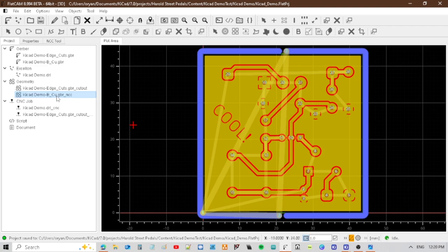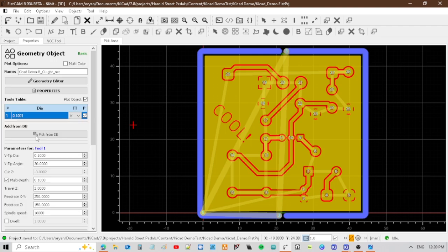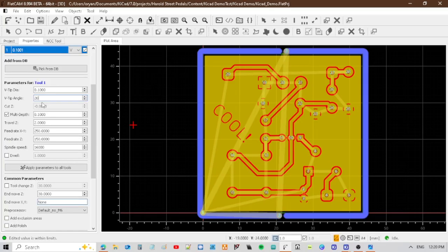So now we got to make the G-code. This is where we keep our tool the proper size. We don't put the 1 here. We keep it the proper size. Mine is a 20-degree V-bit. So you're going to put your own, whatever bit you're using, that's what you put here. So if you have a 0.2 30-degree bit, put that in. Don't use my numbers. Use your bit size.